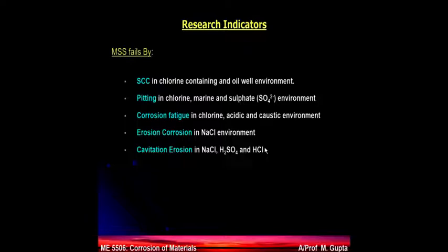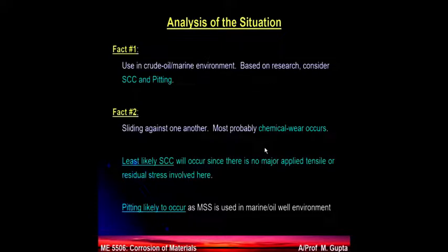We are not talking of stresses on this part, so this is ruled out. We are not talking of repeated interaction of the metal or cyclic loading. This was ruled out, and we asked them whether there are solid particles in there, and they said no. So erosion corrosion is ruled out. So it was a continuous interaction between the industry and us. We said these are the possible ways, then based on the questions we asked, they gave us the answers, and we narrowed down to pitting corrosion.